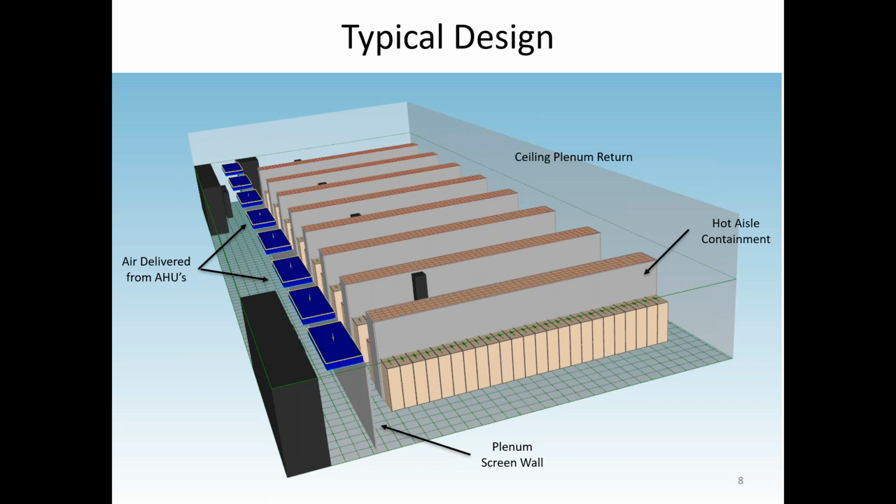You can do that. But remember, you want to boil the model down to the simplest representation you can possibly make and still have it relevant to the question you're asking. The model should be as simple as possible, but not simpler. It should try to capture the physics that you're trying to capture, but does not need to be more complicated. Because these units are expected to be individual air handlers, you can turn them on and off in any kind of sequence you want and do N+1 studies.